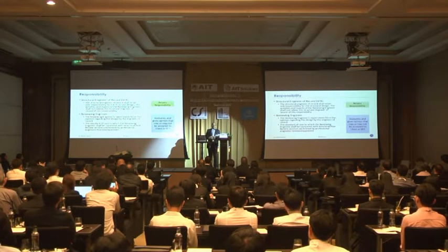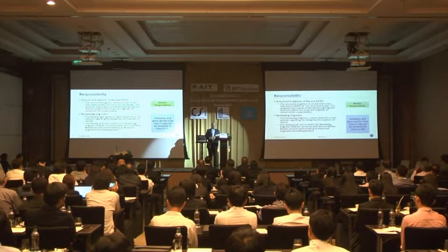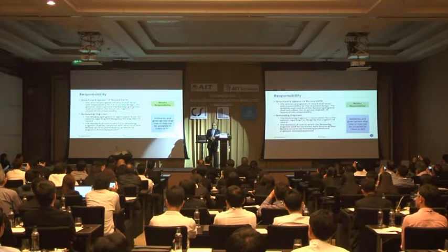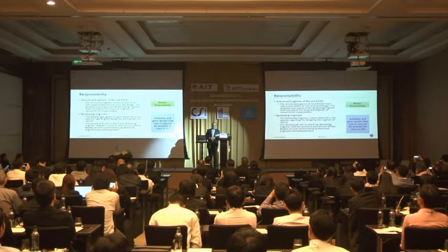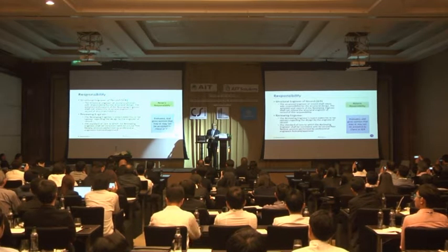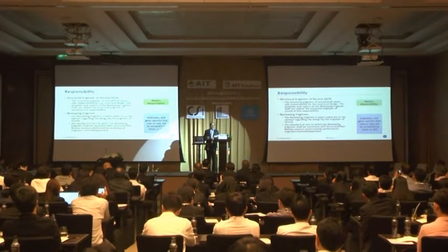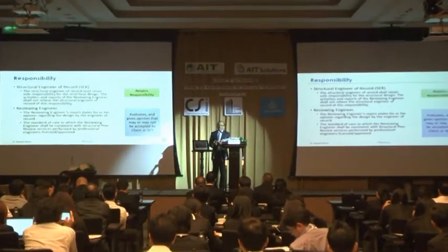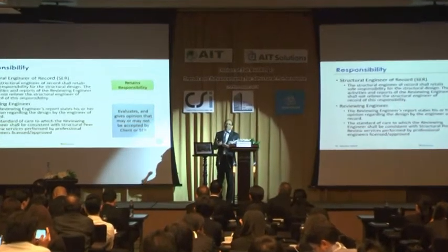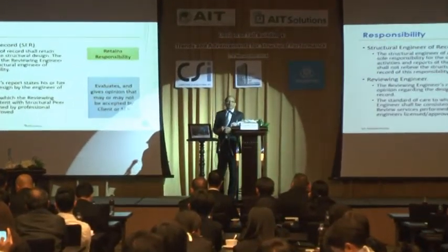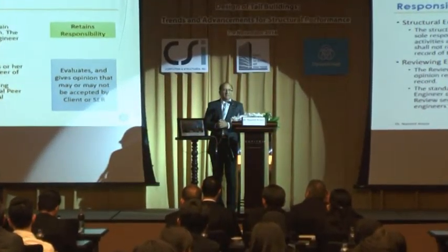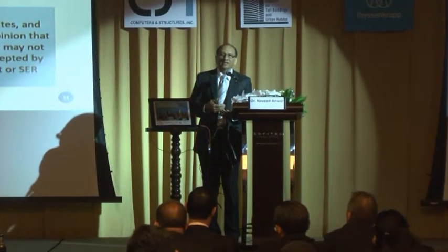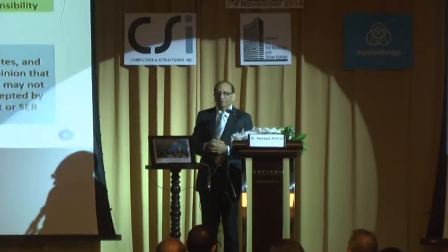However, the responsibility of the peer review does not shift. The engineer of record still retains the responsibility of the design, because the peer reviewer can only recommend, can review and give comments, and does not have the authority to change the design. The comments by the peer reviewer may or may not be accepted by the client or by the engineer of record, which is fine, but at least they are made and they are evaluated.